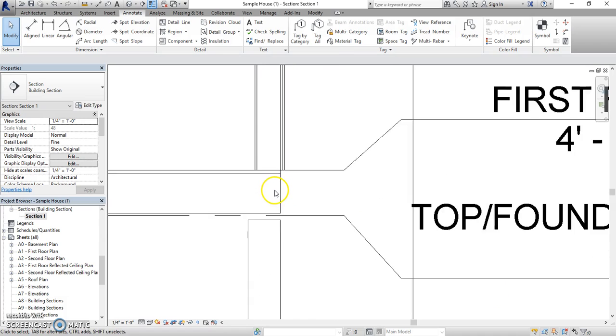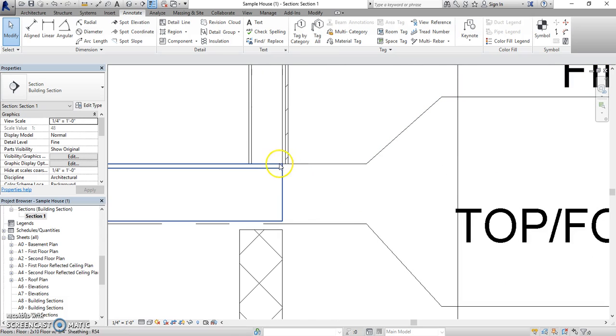Now, one thing that's important is that you have your first floor level and your top of foundation wall levels set so that the gap between them is correct for all of the geometry to fit. So we have a 1.5 inch sill plate we're going to put in. We have 9¼ inch joist, 2 by 10 is 9¼ inch, plus 3/4 inch sheathing, which means that we're going to have 11.5 inches between the top of foundation wall and the top of the first floor.